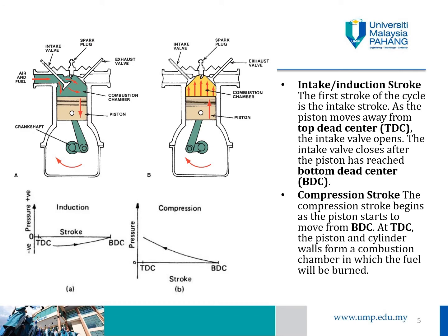So the common movement of an engine is there is an intake or induction stroke, and here the piston goes from the TDC or top dead center. The intake valves are open and the intake valve closes when the piston reaches slightly below BDC. Okay, and then there is a compression stroke which begins as the piston starts to move from BDC to TDC again, and after that combustion occurs and the fuel is burned. So this is the two strokes for induction and compression if you look at the picture A and B.